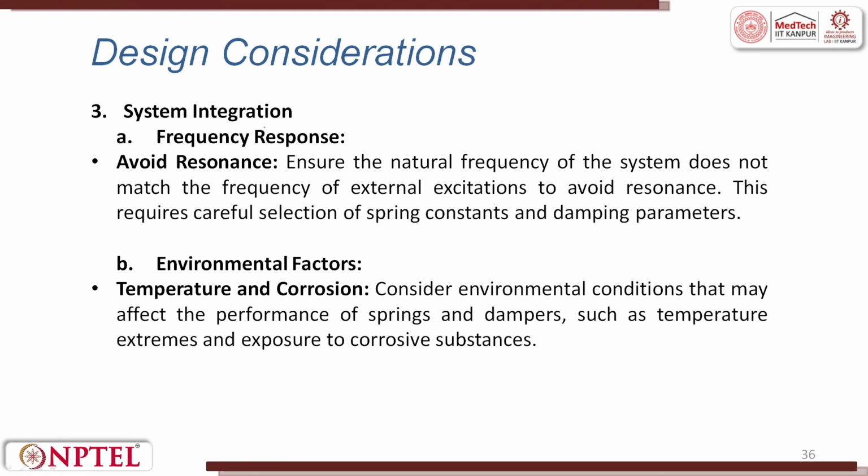System integration depends on two things. One is frequency response, which is to avoid resonance. Ensure the natural frequency of the system does not match the frequency of external excitation to avoid resonance. Environmental factors such as temperature and corrosion also play a very important role while considering the design. Temperature and corrosion are environmental conditions which may affect the performance of a spring or a damper.